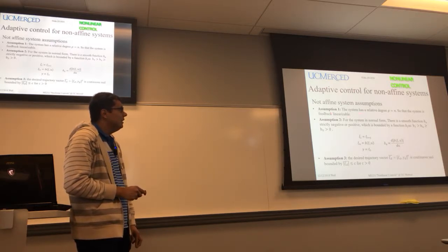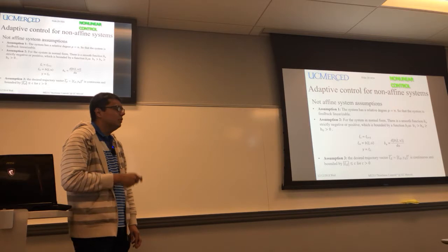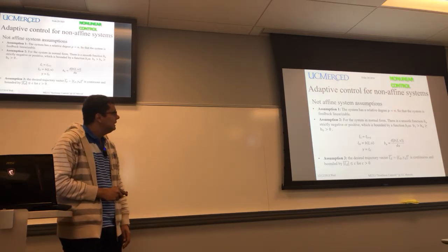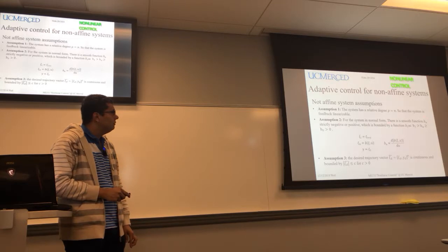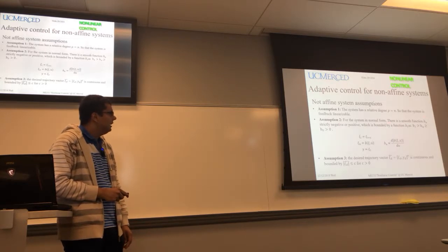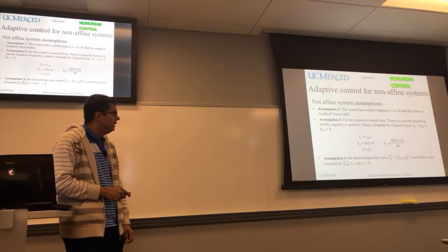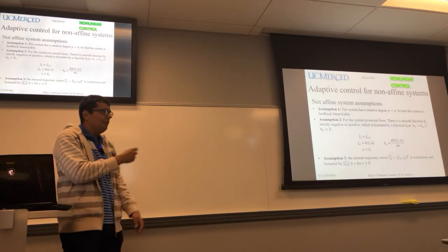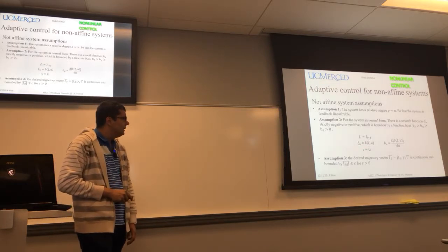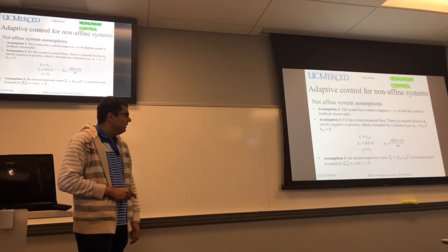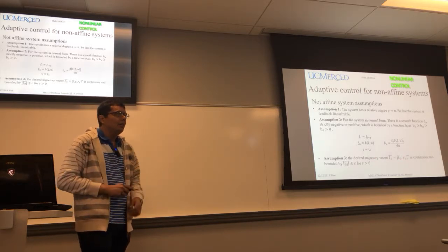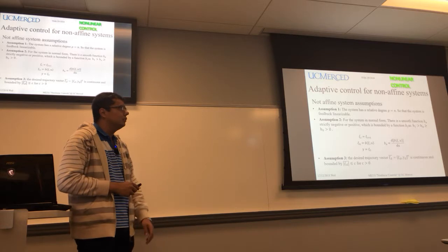The system has a relative degree rho equal to n, so the system should be in the controller form or the normal form. If the system is in the normal form, the last state should be strictly negative or positive and should be bounded, the same as the previous elements. And finally, the desired trajectory vector is that one and is continuous within the compact set of operation of these controllers.